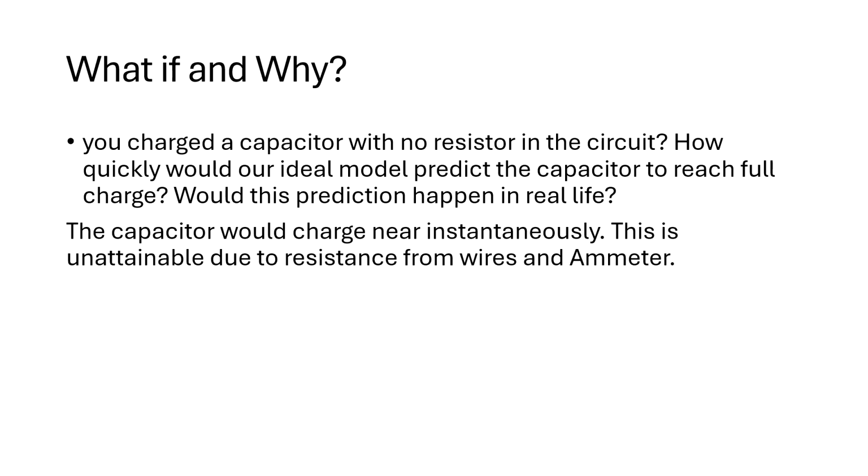So for our what if and why question: if you were to charge a capacitor with no resistor in the circuit, how quickly would our ideal model predict the capacitor to reach full charge? Would this prediction happen in real life? Theoretically, the capacitor would charge nearly instantaneously, but due to minor resistance in ammeters and wires, it would not be able to charge instantaneously.